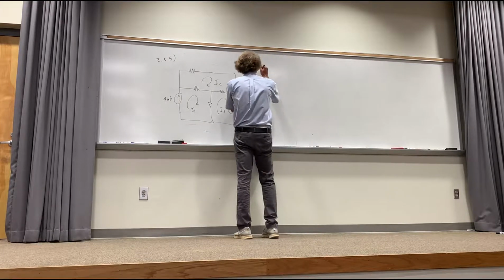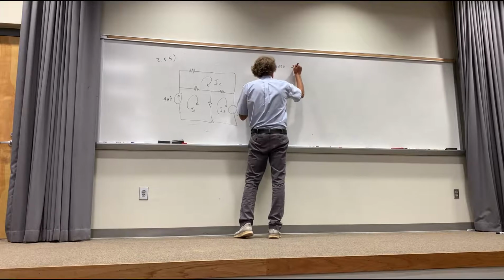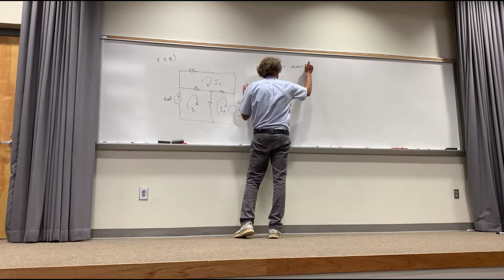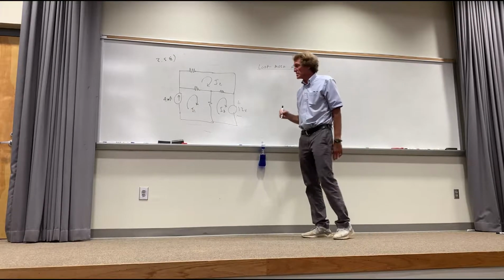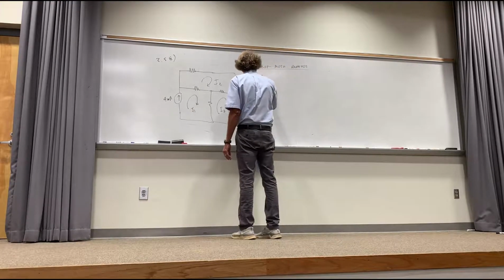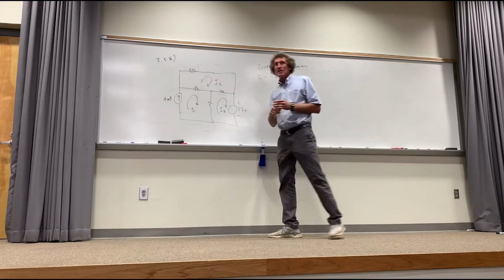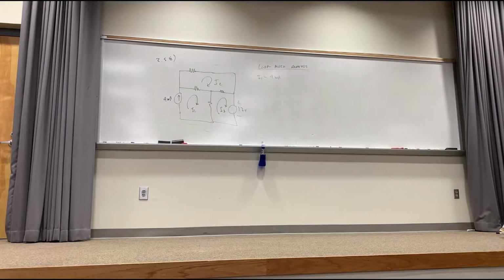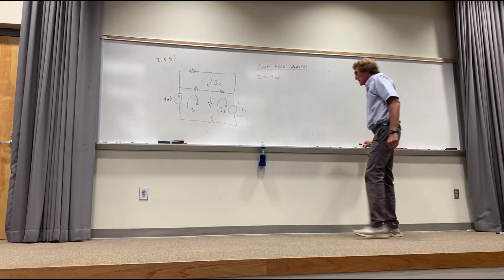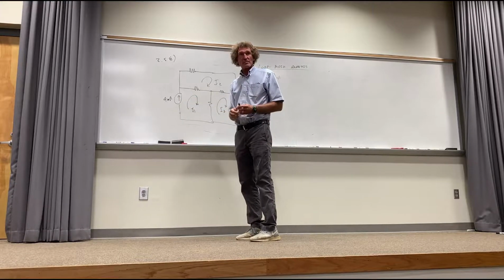All right. Now we're going to use Kirchhoff's current laws, and this is going to be done with loop or mesh analysis. Very first thing, by inspection, can everybody see that I1 is defined already as 4 milliamps? Look around here. This submesh has only I1. It's 4 milliamps. Got it, class?